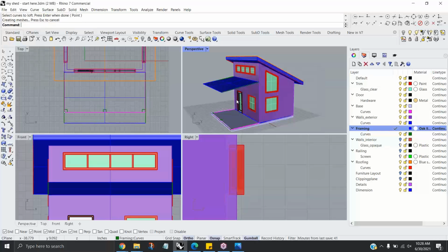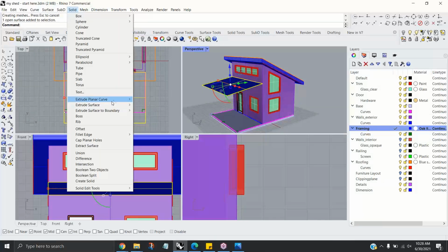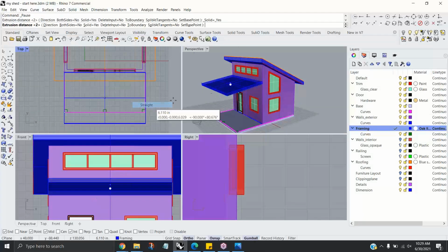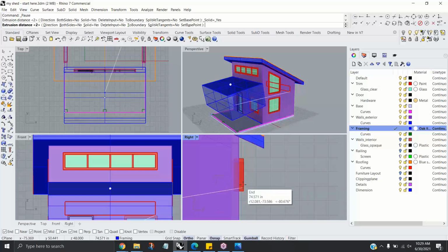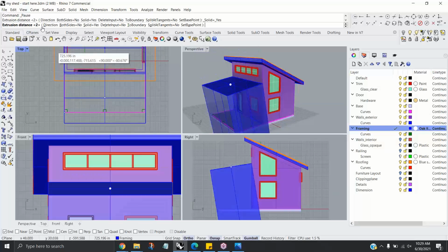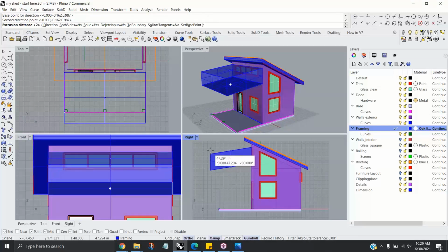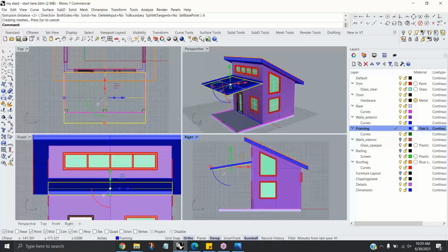Now that we have the surface, we're going to extrude it. Solid, extrude, surface, straight. And remember what we did before? Okay, we didn't want to extrude it like that. We wanted direction. We pick here, and then we pick vertical. And that's where we can type in 6